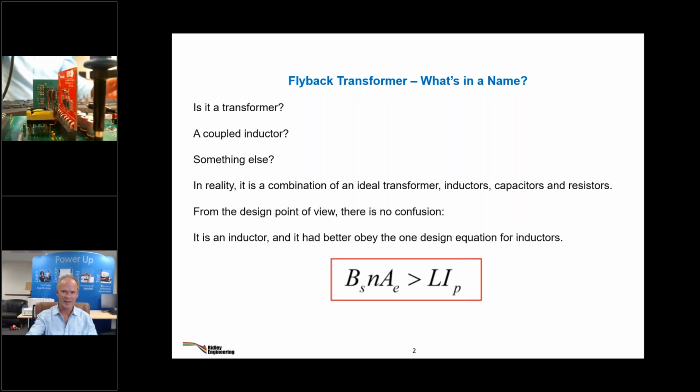Once you part your magnetics, glue them all together, you've got to stop the windings from moving. A flyback transformer is built like a speaker coil. It's supposed to make a noise when you excite it. That's what it's for. So if anything can move, it's going to move. So stop it moving, just stop it hissing. But you try to clean up the waveforms first to stop that sporadic operation. Very often you can't do that. So hopefully that answers that question.